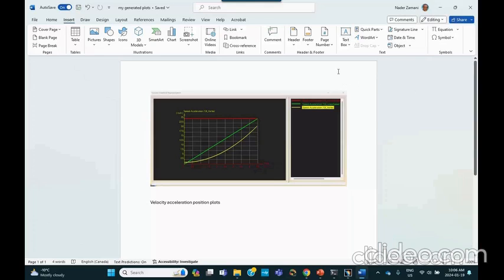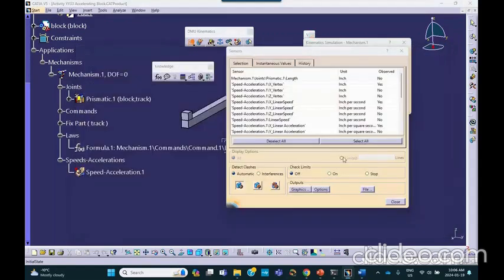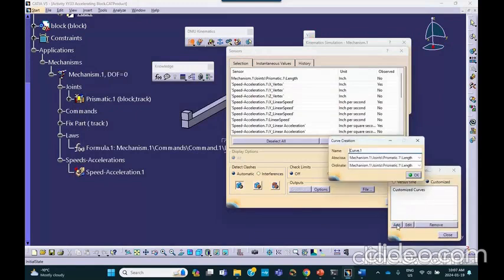Acceleration versus velocity is just going to be a horizontal line, just like that. But I want to generate it. So we go here, we close that. We're going to say options, customize, add. You can call this thing curve one or acceleration versus velocity.